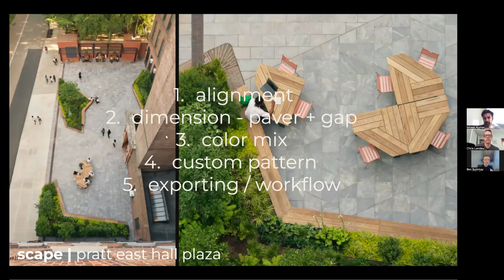And if you need to make any adjustments, it's automatically trimming out those pavers, maintaining those paver dimensions all at the same time while you're moving around these edges to make sure the angles match up, or even rotating each of these individual areas so that the alignments for each area is appropriate. And so the paving workflow really solves a lot of these problems quickly for you, and saves that time for you to be able to iterate through the design ideology, and really have a heavier hand on the design side as opposed to spending all that time doing this little nitty-gritty scaling.